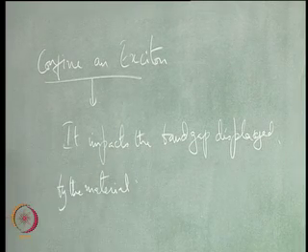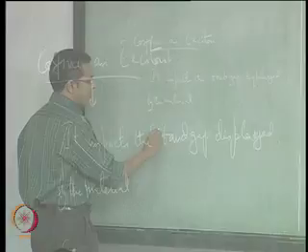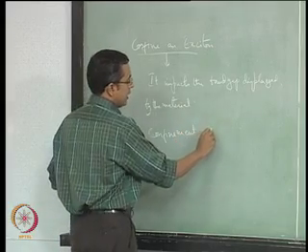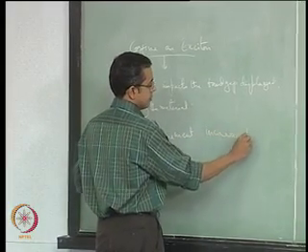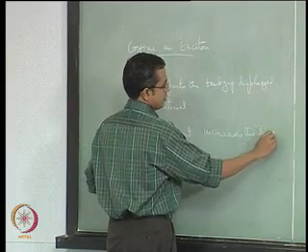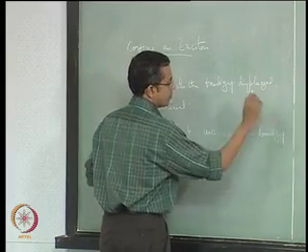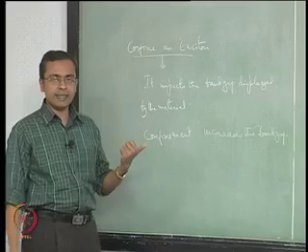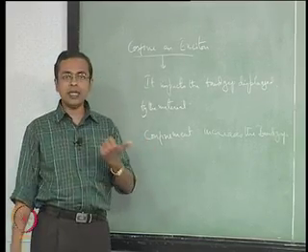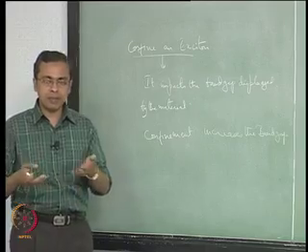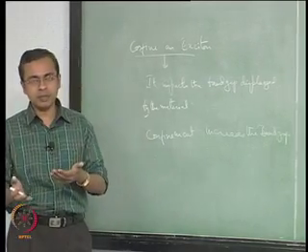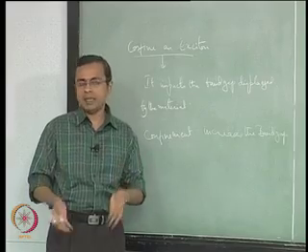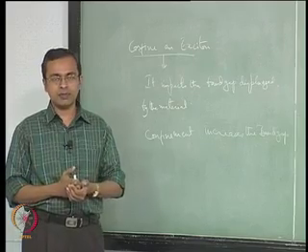So it impacts the band gap displayed by the material, and in general confinement increases the band gap. Okay, so it increases the band gap. Now this is of a lot of interest, because what this means is you can say for some particular purpose you wish to have semiconductors of different band gaps arranged next to each other, so that you can make specific semiconducting devices.